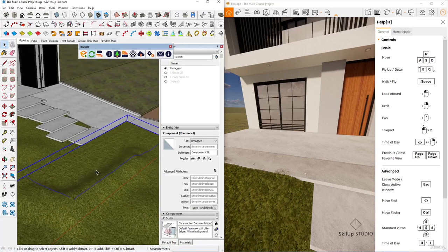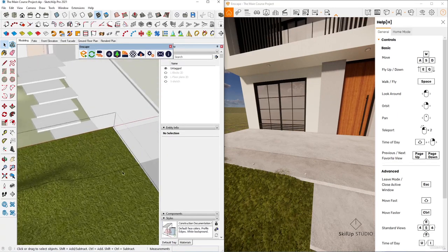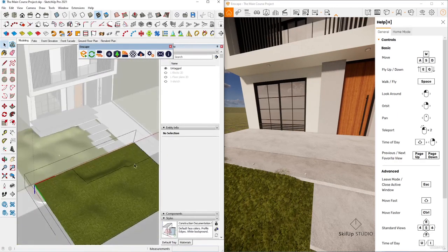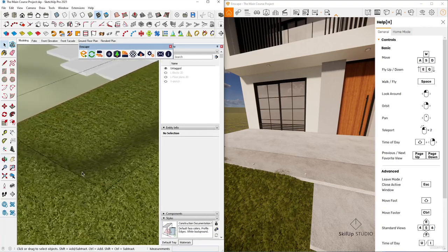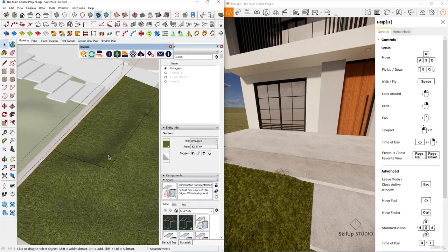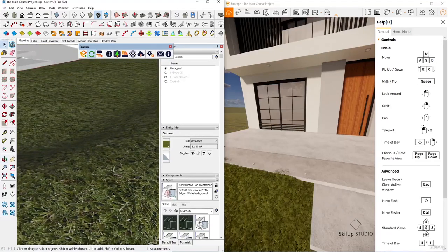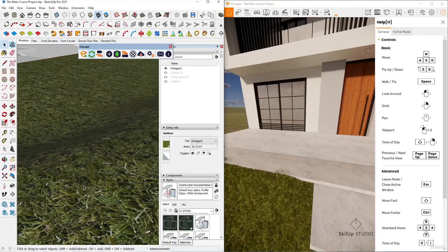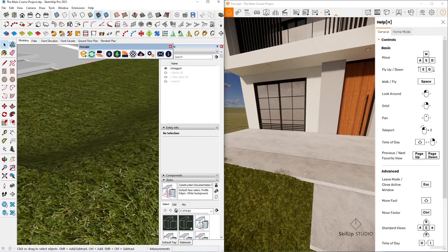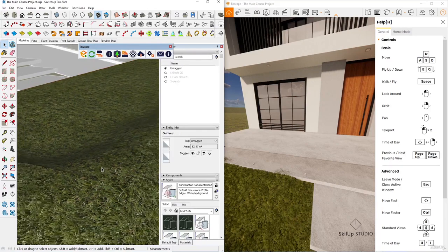I will check on it to make sure that it's a closed shape. I found this open. We need to close it. So to complete this line, we will turn on the hidden geometry. Then select this edge here. Then uncheck soft and smooth. Thus turn off hidden geometry.